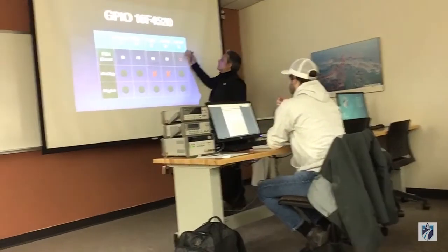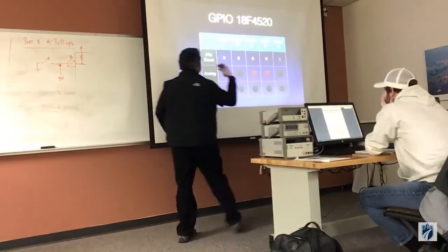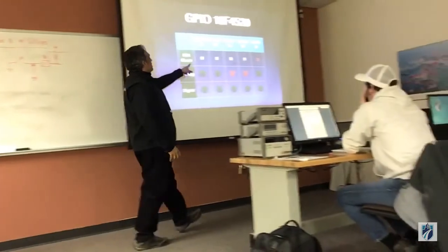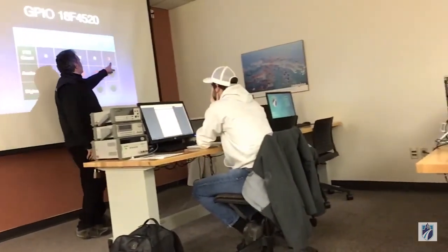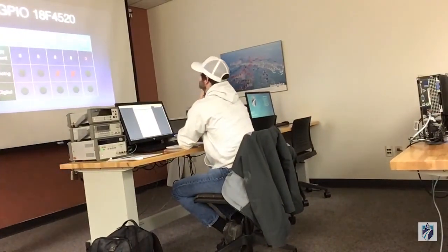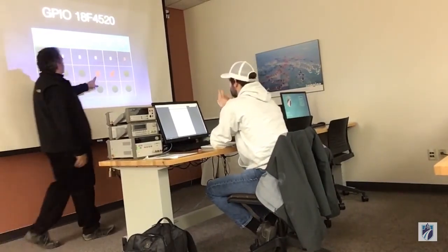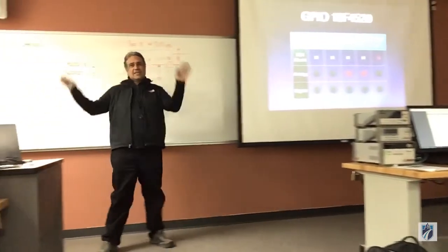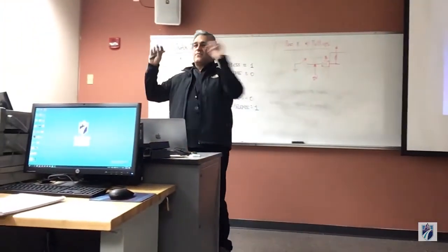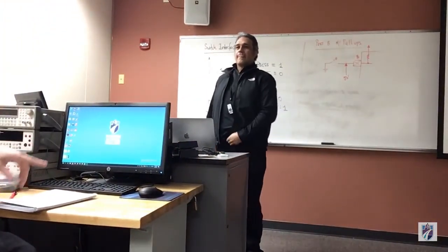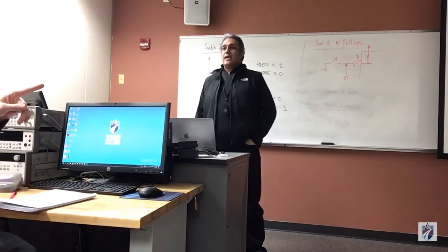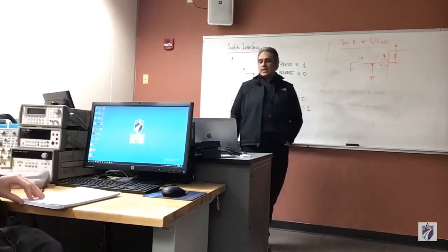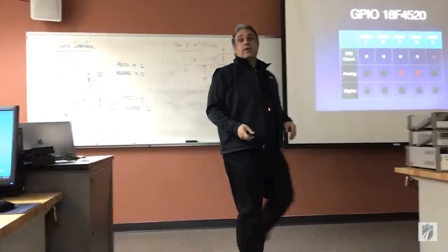You got 5 ports. Port A, B, C, D, and E. The pin count on port A, B, C, and D are 8. Port E is only 3. And you have analog and digital everywhere except port C and D that are fully digital. Right? Any questions on that? Kind of like straightforward. Yeah? Didn't we start the lecture with you saying there's 40 GPIO? It's a 40 pin 32 GPIO. Oh, okay. Yeah. Okay, so here's the fun part.